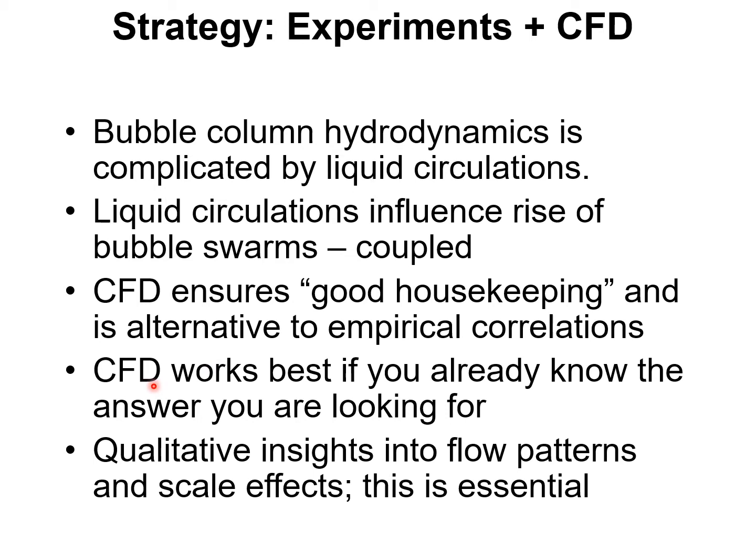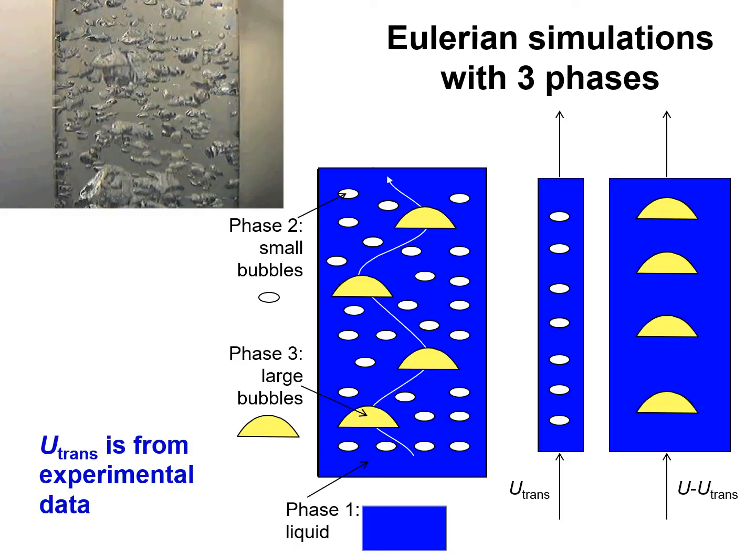This is a tongue-in-cheek remark which states that CFD works best if you already know the answer you're looking for. What I'm trying to say is that you need to have an intuitive understanding of scale-up phenomena based on cold flow studies before you can trust your CFD simulations. Once you gain trust in CFD simulations, then only can you proceed to scale up. So qualitative insights are essential.